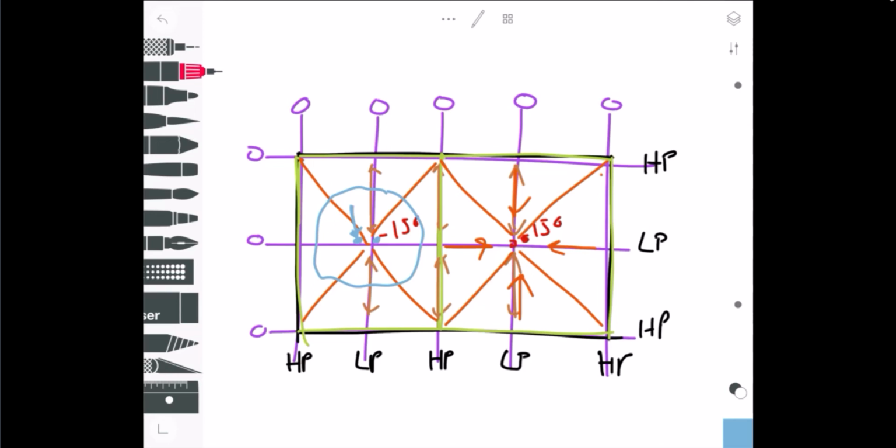And so I always get asked, where does a 150 come from? I'm not 100% sure. I know at one point when I was working on buildings, we always wanted to try to achieve that 2% slope. So obviously, depending on your grid bay dimension, you might not get that 2% slope. So sometimes we would say, well, instead of 150, let's take it down to minus 200 to get that 2% slope. And I don't know where it came from. It might have been the plumbing code or something, but it was from the mechanical engineer, I'm sure, where at some point there was a requirement that you couldn't have that emergency overflow more than 150 millimeters high.